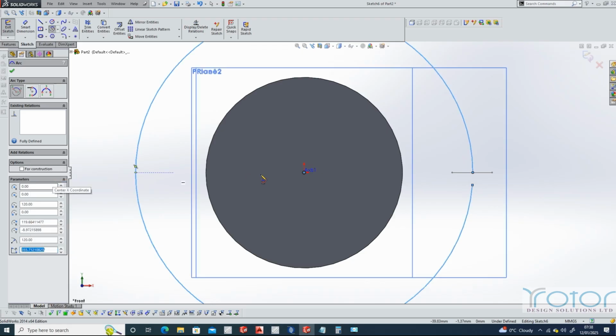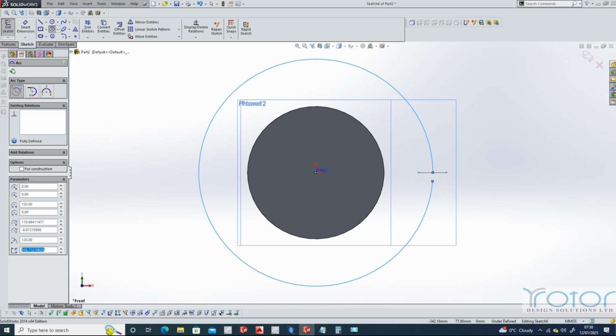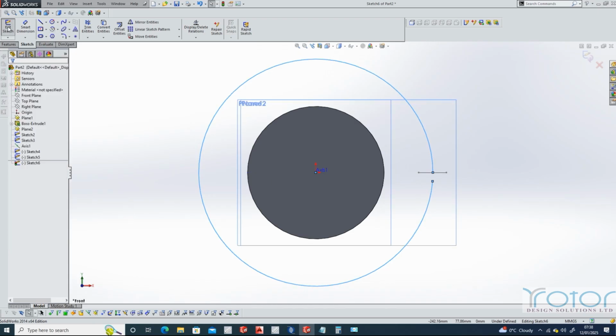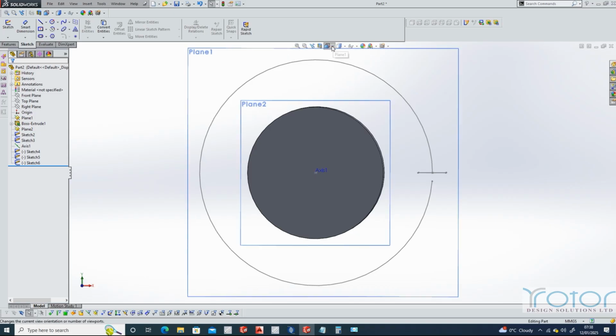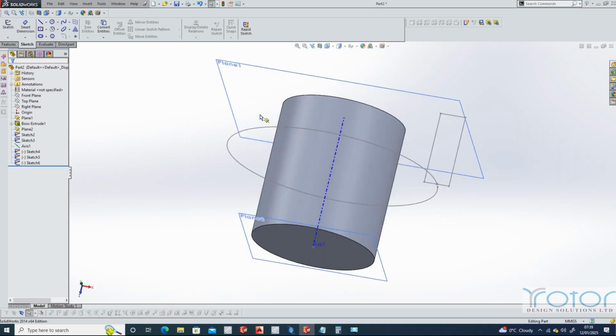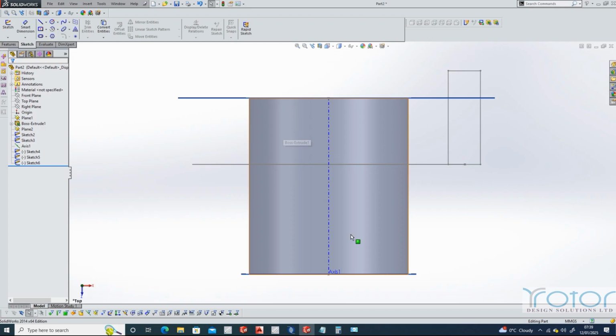Okay, and the important ratio for the rotor geometry generation is the ratio of the number of points on the star and the number of flutes on the rotor. So for this particular design, I'm going to use 11 points on the star and 6 flutes on the rotor.